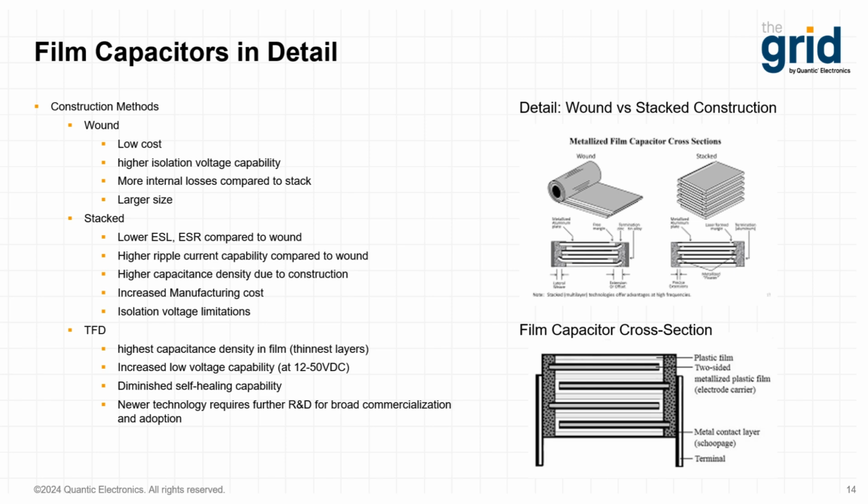Mechanically, it's a stack construction, but the construction method is different. So this allows for the thinnest possible dielectric layers, sometimes less than 1 micron, and capacitance densities rivaling those around MLCC. This is the newest construction method applied to film capacitor technology, and as the methods are refined, we can expect broader adoption of this technology in the market.